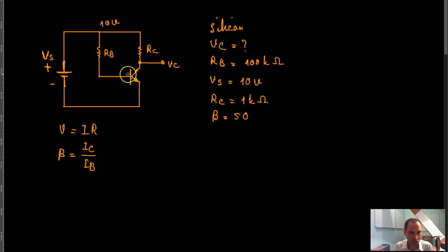The base current changing is automatically going to change the collector current, because the beta of your transistor is going to determine what sort of collector current you're going to have based on your base current. And that is based on this algebraic equation that basically beta times I of B is equal to I of C, meaning that whatever sort of I of B you have, and that you can control, of course, using this resistor,